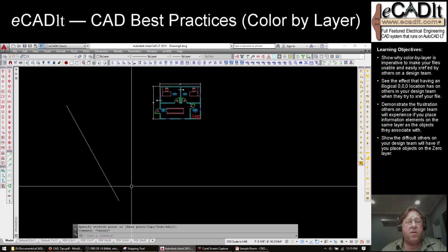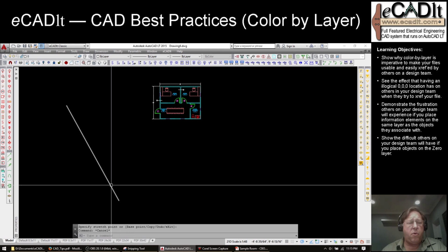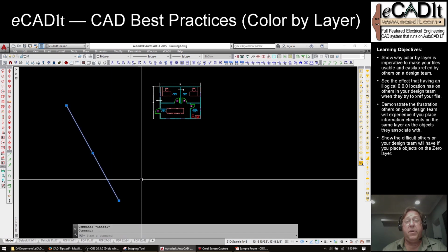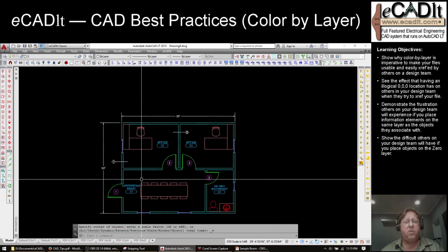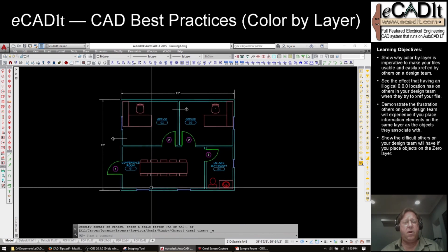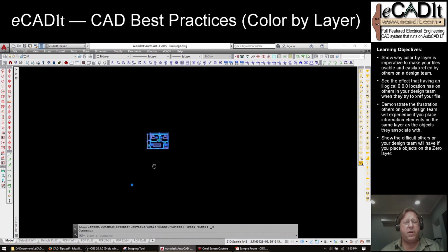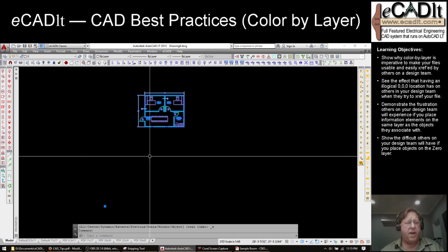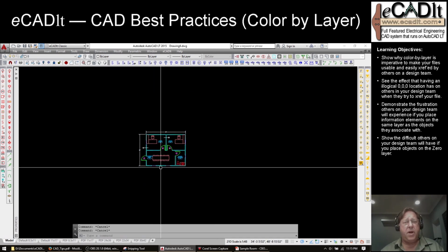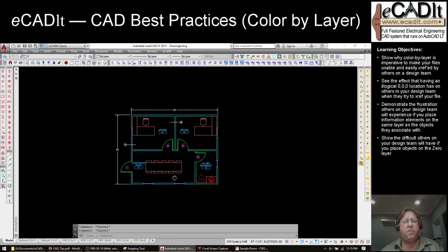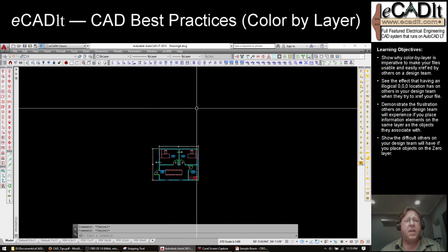So that particular designer didn't use a 0 point, so when I XREF'd it in, it came in 50, 60 feet away, but it could have been 50, 60 miles away. But nevertheless, it works, right? I can still work with it, even though it's not at the 0 point. When I select it, I see that its insertion point is down there at 0, but it itself is off in space. But not a big deal, right?